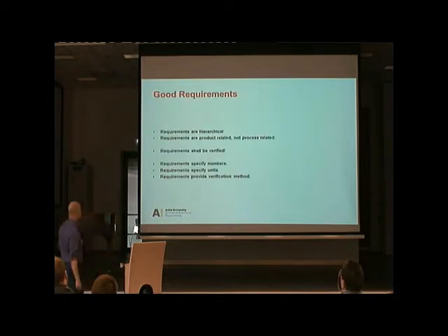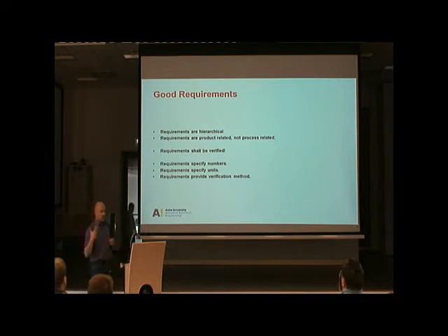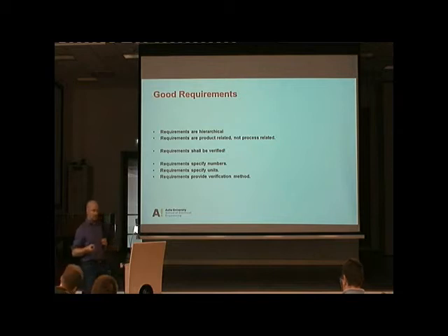So good requirements are hierarchical. For example, you need to specify that we need to make this measurement from a 700 kilometers circular orbit. This is a requirement. We need to be there to make, for example, electron flux measurements at 700 kilometers. Easy. But this requirement gives you a whole series of implications. So you need to get there first. You need to get to 700 kilometers.